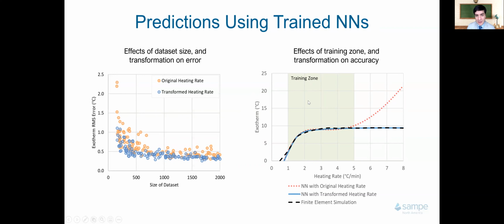If you look at the other curve, it shows the predicted exotherm for a case compared to if you give different heating rates. So imagine you have a thermal stack, heat transfer coefficients and thicknesses, and you're changing the Q cycle for that. Go lower heating rate, higher heating rate. You're really looking at how much exotherm I'm getting. So this is the exponential response I was telling before.